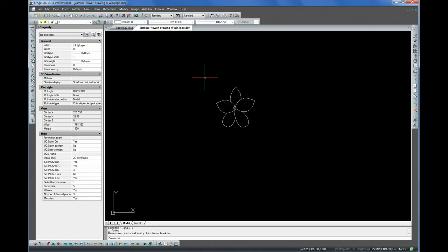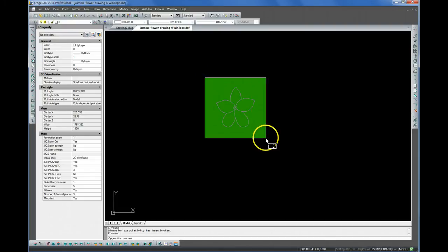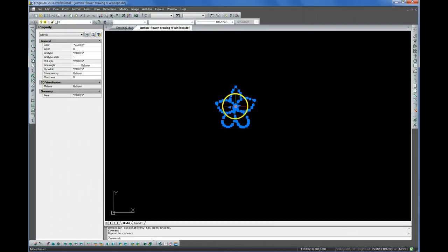We could, of course, scale within SolidWorks as well. Sometimes it's nicer if you get it to a reasonable size beforehand. So I'll just show this. You don't have to do it if it becomes confusing. So I selected everything. Then there's this command called scale. So you can either type scale or hit that button.